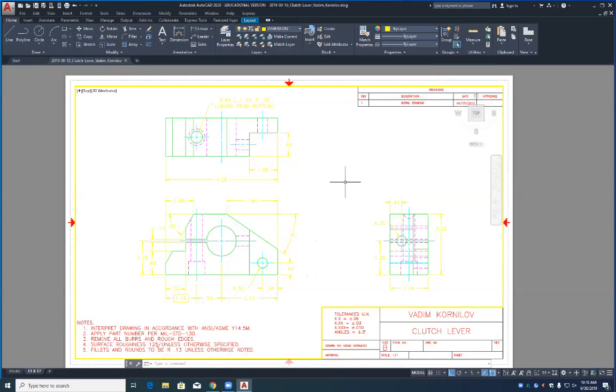What is the keyway note on the lever hub? Oh, 3/8 by 3/16. What relationship is 3/16 to 3/8? It's half of it. Does that make sense? That's how keyways are specified. Okay, so it's half of the overall width.